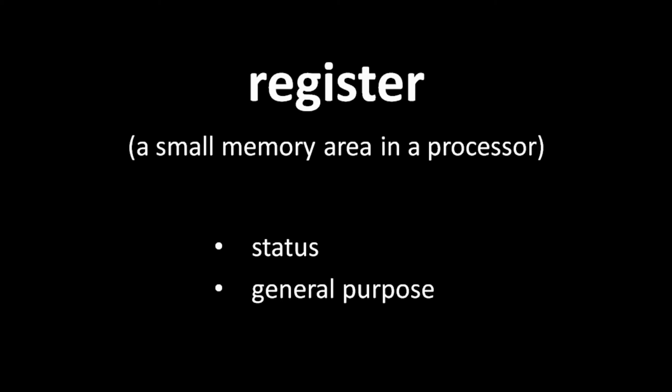Today's x86 processors contain a few dozen registers, which is on the low end for high-performance processors. So if these CPU registers can't store much data, why do we have registers? Well, most CPUs can only perform operations on data in the registers, not in memory. Addition instructions, for instance, generally can only add numbers in the registers, not numbers out in the system memory.